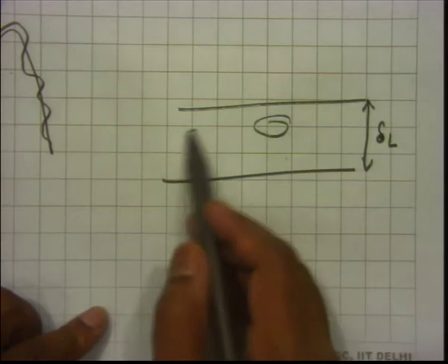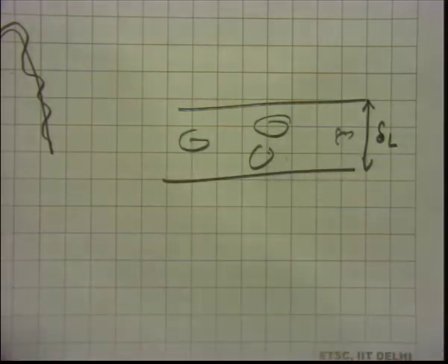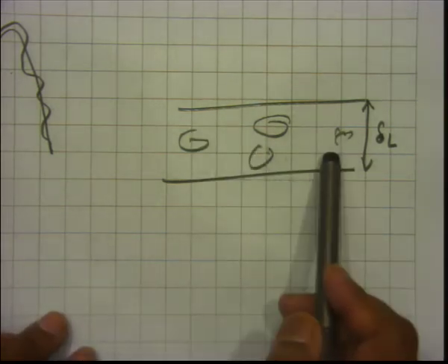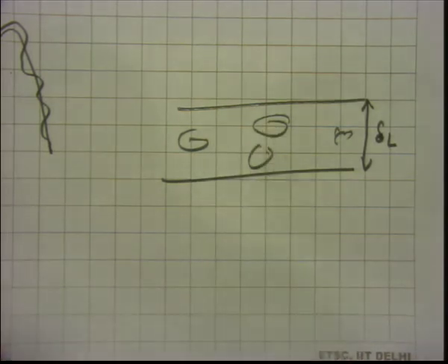The eddies, the turbulent fluctuations and the vorticity, they will affect the processes in the flame. They will affect how reaction takes place. They will have an effect within the flame thickness. They will affect the mixing of fuel and air. It will affect a lot of things. So, that is one kind of effect.